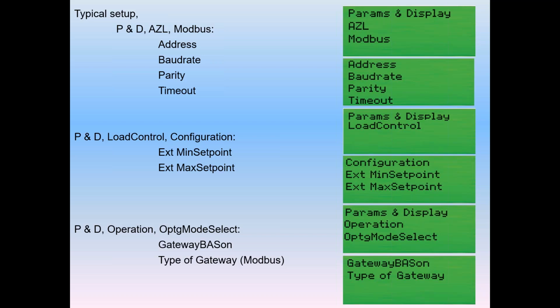The LMV5 also carries a second protocol thought to be popular in Europe, an eBus, but quite frankly, even in Europe, Modbus is the accepted standard. Modbus is an open protocol environment and is very common and the most popular one used.